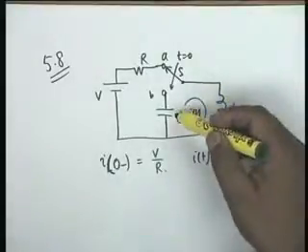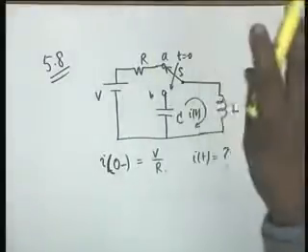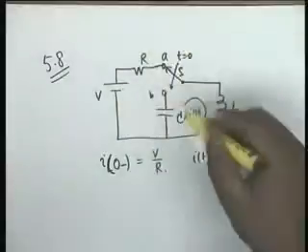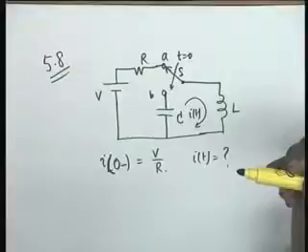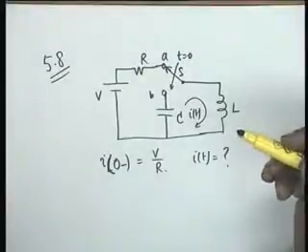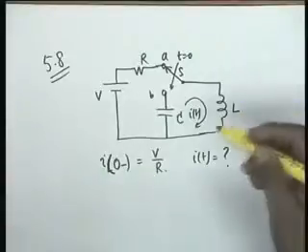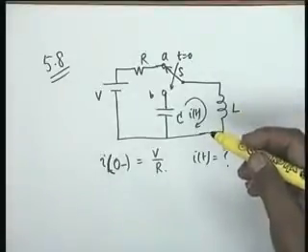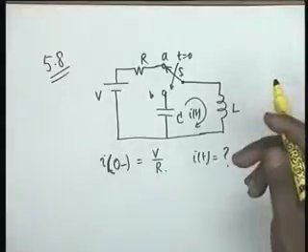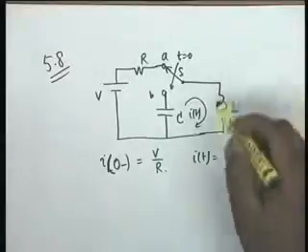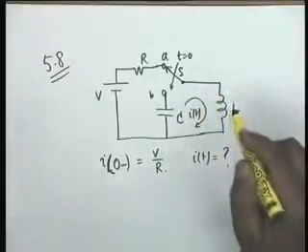The capacitor now, it is a steady state. The capacitor immediately starts discharging through L, and this process continues. It is a seesaw situation. In other words, you will get pure oscillations. Now, as I told you, this part of the circuit is a passive circuit.